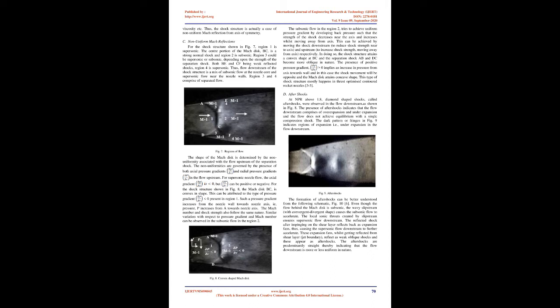A convex-shaped Mach disk, A, was formed, with height H as the height of the Mach stem, i.e., the normal part of the Mach disk. The first foot of the lambda shock, i.e., the starting point of the incident shock, the separation point, induced a strong adverse pressure gradient, which was strong enough to cause boundary layer separation, as shown in D.